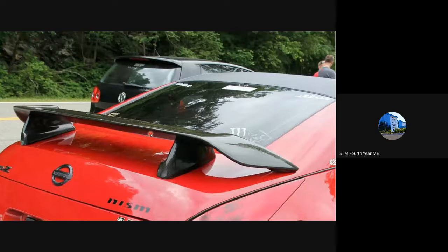But in the case of a car spoiler, you can see the inclination is in the opposite direction compared with the aerofoil of an aeroplane. When the air comes here, it hits this plane first and then goes underneath. So a region of high pressure will always be created above the spoiler rather than below it. On top of the spoiler a higher pressure will be generated, while at the lower portion there will be a lower pressure region. Due to the higher pressure moving to the lower pressure region, a negative lift is created at this spoiler.